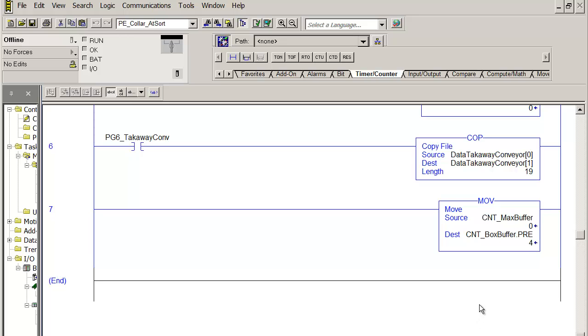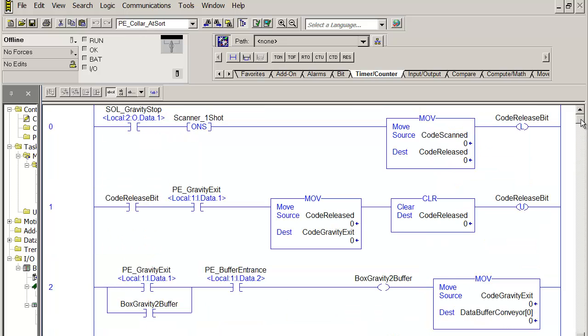Okay, we're going to pause, and I'm going to then move on to creating multiple programs. But here's the deal. We have 10 of these in our system, 10 conveyors like this. It could be 20, it could be 7. But we have multiple conveyors, and they are identical. Now, the data images are identical, but the hardware images are not. They look the same. They have the same part numbers for photo eyes and solenoids and motors. The problem is they're wired to unique inputs on the I/O cards.